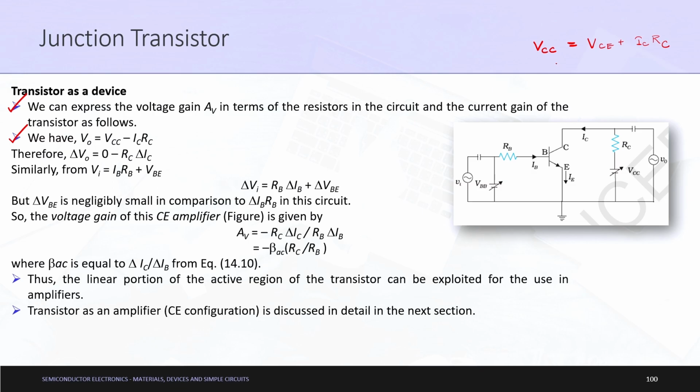Okay. So, just changing it a little, we finally obtained that VCE is nothing but your output voltage, correct, because this is the output which is being obtained across this device which we now require. Therefore, this VCE is nothing but V0, which can be written as VCC minus ICRC. So, that is the first concept.